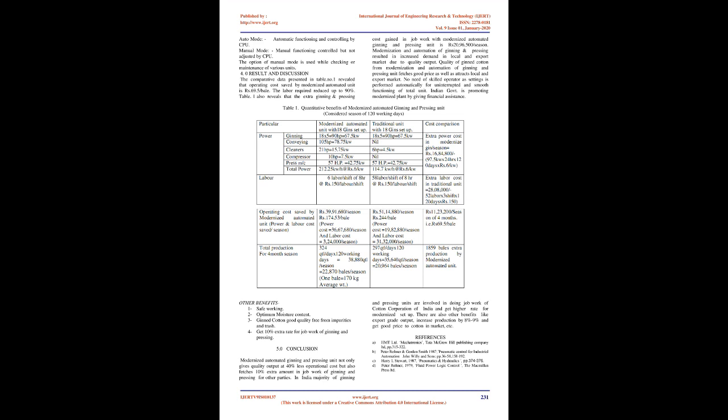5. Moisture meter and humidifying system. The moisture content of the cotton in the storage house is checked by an online moisture meter from the sample given by a flow sampler, which takes samples periodically. As per the signal of the moisture meter, the desired moisture is added to the cotton in the storage hall. See Figure 5.